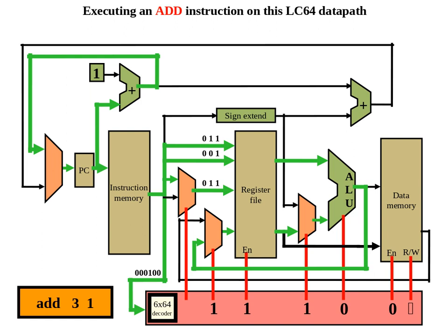Why do we have 2 muxes? Well, one's coming from the ALU, the other's coming from data memory. In other words, this mux is determining if we are writing to the register file from the ALU or from the data memory. If we are trying to send something to the register file, we may want to send the ALU output or send memory. How do we determine? We use the mux to determine which output is being sent to the register file.